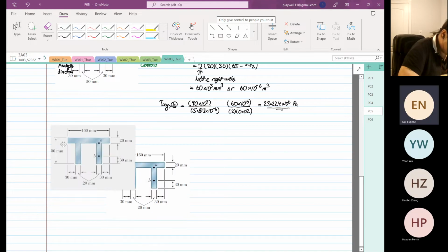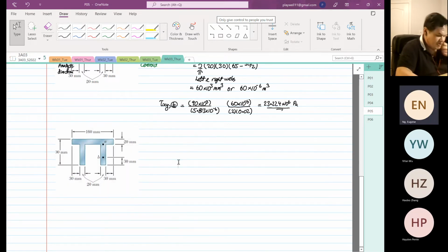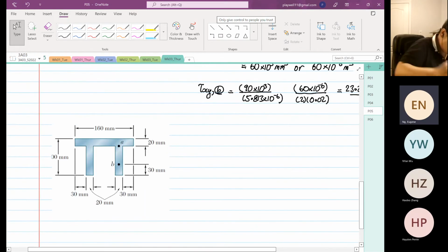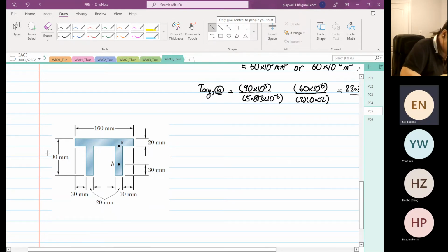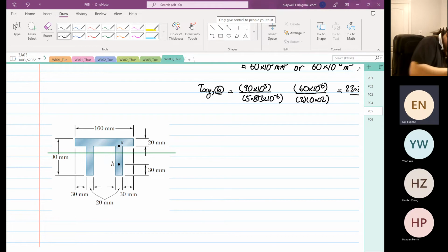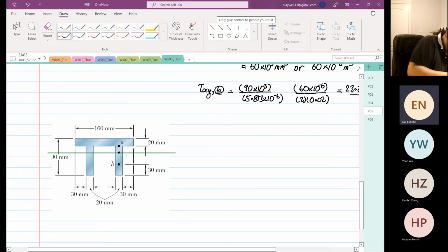Okay, there's something I want to show you that is important down here, okay? So what we are going to do now is we are going to determine the shear stress at the centroid. Okay? So I'm going to introduce a new point I call point C. Okay, and this is our global centroid.